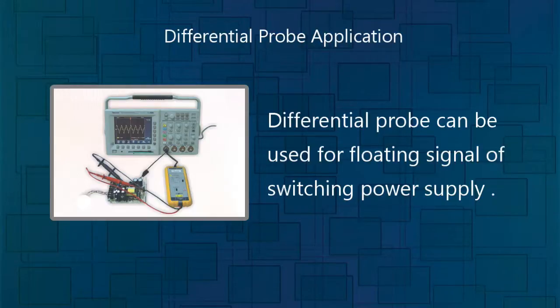In recent years, high-speed digital circuits are widely used in digital circuit design and digital transmission, and there are lots of high-speed differential signals. As a result, a new type of differential probe was created. The voltage measuring range is very small, around a few volts or even millivolts or microvolts, but the bandwidth is very wide, up to a few gigahertz. In oscilloscope measurements now, whether it's the high-voltage differential probe or the high-speed differential probe, in their respective fields, both are essential.